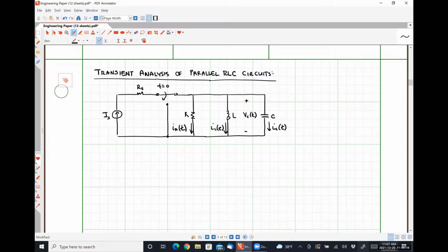Okay. When that switch opens up, that effectively disconnects the RLC circuit from the current source side, and we should see that our inductor starts transferring some of its energy to the capacitor and to the resistor. So it's very similar to what we saw in our transient analysis of first order circuits, so RL and RC circuits, but now we have an extra energy storage element where energy can just be passed back and forth before everything gets converted to heat by the resistor.